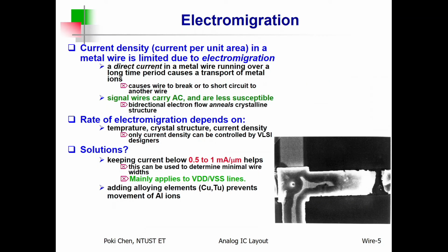All right? And then allow me to remind you again, I think we talked about electron migration or metal migration in chapter 4. But here again, I would like to emphasize for such kind of wires, especially for metal wires, you need to pay much attention to the width of the wires. Actually, you need to know the peak current. Okay, this is what I need to emphasize again. For each wire, you need to pay attention to the peak current the wire would carry. And after that, you need to set the width for the wire. Usually, for each milliampere, you need 1 micron. That is the easiest way.